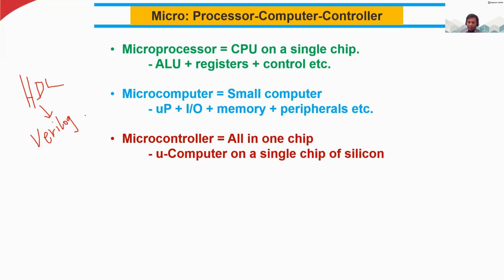Then you do the synthesis of this code using some specific technology library. Then you do pre-simulations and post-simulations, and check that the timings and clocks are working. If everything is okay, you send the final file to the factory, the fabrication house. They fabricate it in terms of chips. That is the microprocessor.